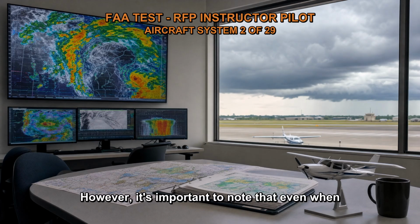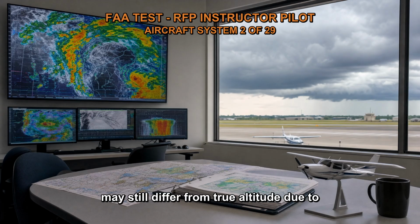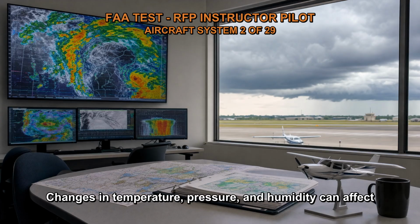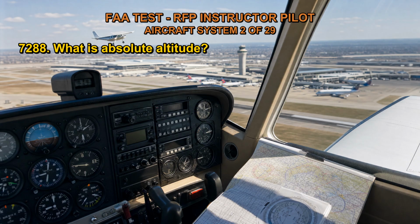However, it's important to note that even when the altimeter has no mechanical error, indicated altitude may still differ from true altitude due to non-standard atmospheric conditions. Changes in temperature, pressure, and humidity can affect atmospheric density and, consequently, the altimeter's readings.